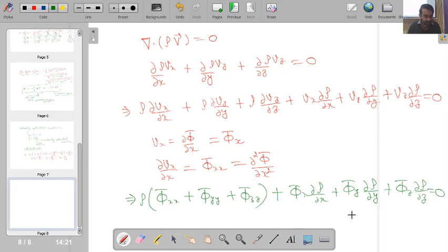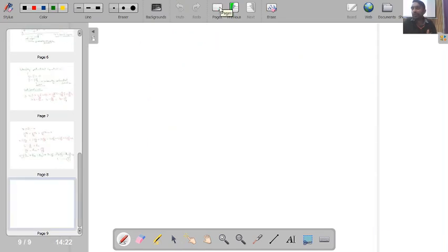Okay. So ultimately, say this is my equation number 4. In this equation 4, I have two additional terms. I want my complete equation in terms of the velocity potential function. I don't want more variables in my formulation. If I want to write this equation entirely in the form of a single variable, here rho is one additional variable and these gradients of rho in different directions are the three additional variables. So we now have to get some equations which can remove these things.